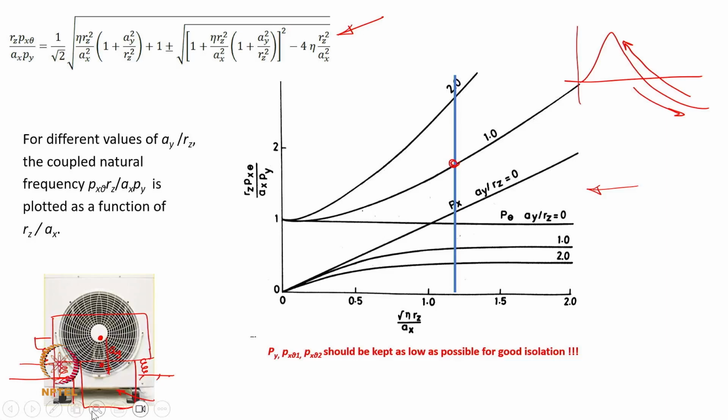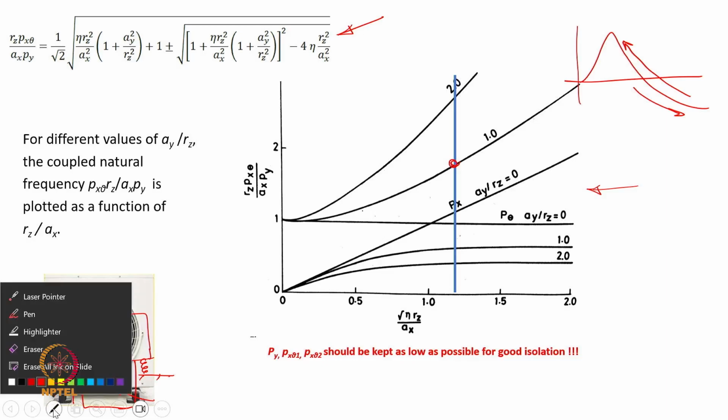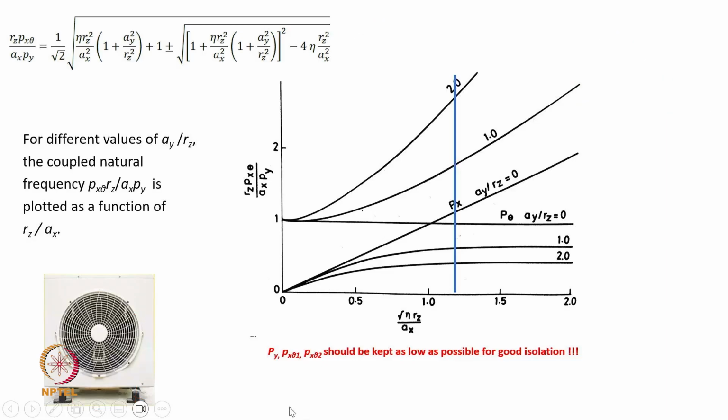So ideally, a compressor, which we have seen, should have been supported here, but of course we don't care so much about noise and vibration in day-to-day life. This design is not going to generate quieter systems. The force going through this mount to the foundation is going to be much larger, and that force is going to create vibrations in the walls, and that is going to create sound inside the room.